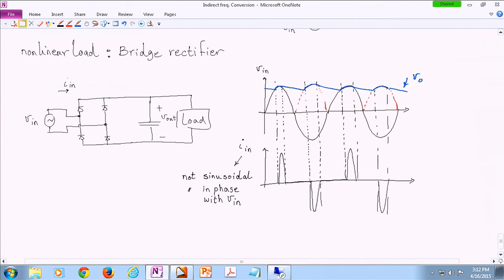So that's actually what we are going to discuss: a few options of providing a power factor corrector. So technically, at the end of this class, you are familiar with a power electronic converter, which turns out to be actually a boost converter that sits in here and basically gives you an input current that is looking much nicer.